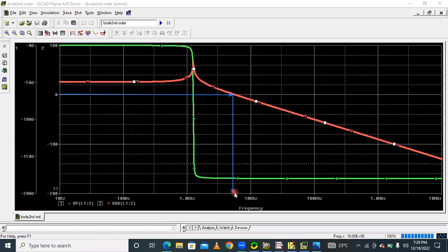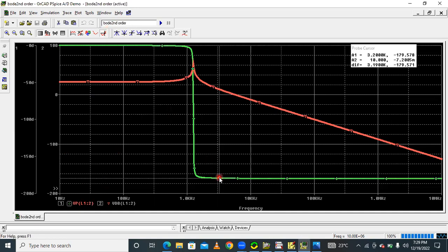So here, this is called the gain crossover frequency. And similarly, this is called the phase plot. In this phase plot, we look at the minus 180 degrees line. So it is up to minus 180, and then select this phase plot, enable toggle cursor, and press here.